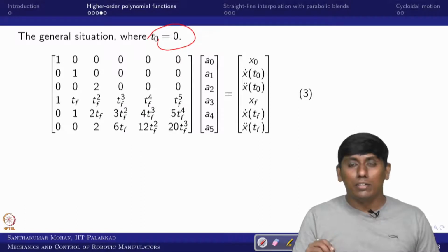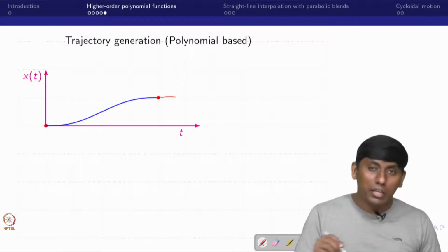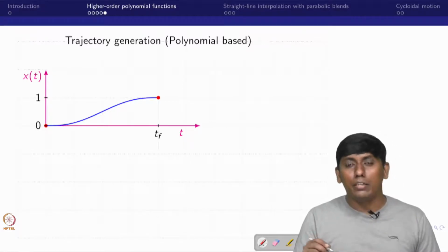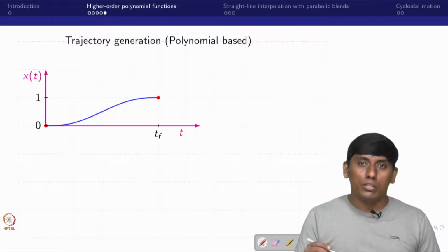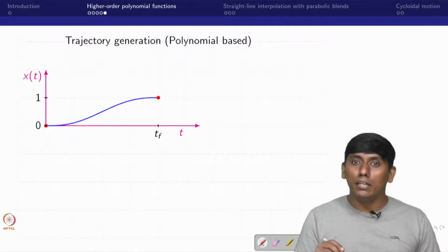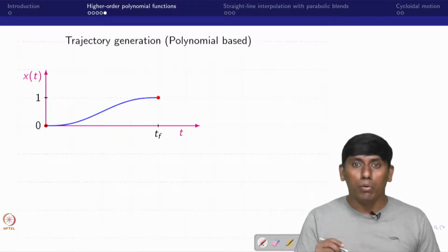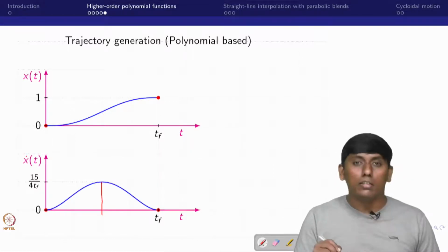Okay, so let us see how the individual velocity and acceleration will go across, again for one unit reading. The profile is a little smoother than the cubic polynomial, which you can all agree on, because the earlier one is a third order polynomial and this is fifth order. But how does the velocity look? We have seen that the maximum is at tf by 2, or tf minus t naught whole divided by 2, in the sense the midpoint. There is the maximum velocity in the cubic polynomial, and here also it is the same, the maximum velocity at the middle point.